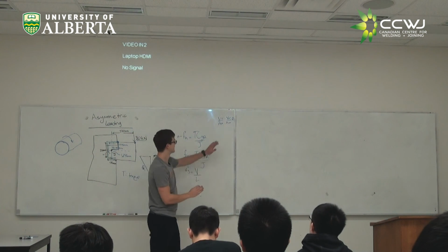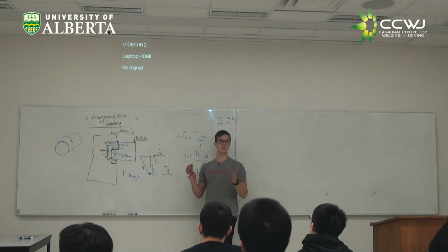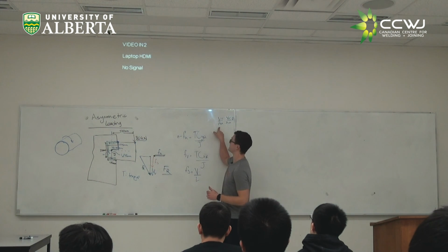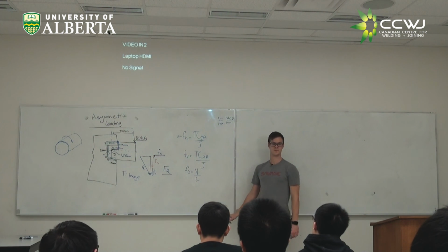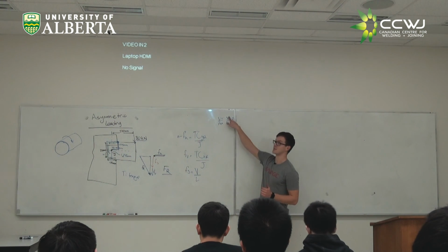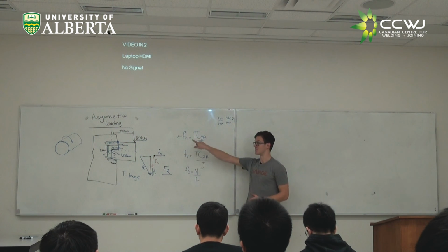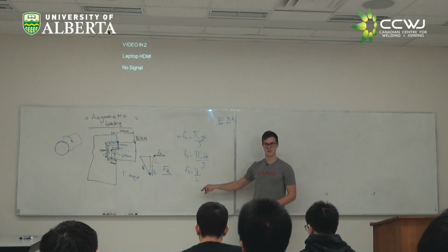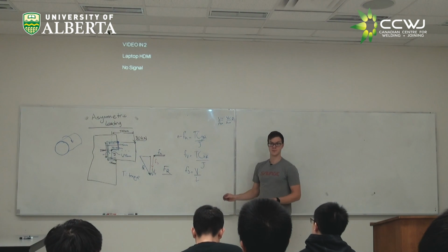If you want to use this approach, instead of having that extra column, it's easier to take your load, divide by your total L, and then compare this VR over AW to your V over L. So if you want an approach that's going to work for asymmetric loads and symmetric loads, rather than having this extra column, it might be easier to always use this formula where you take your vertical load, divide by your total length, and you go right to your VR over AW.